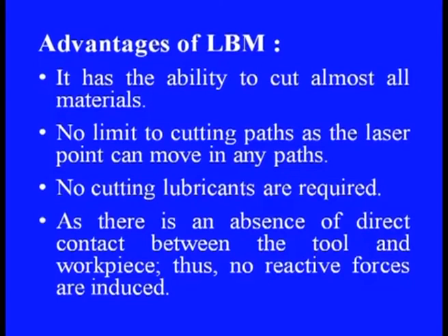As there is an absence of direct contact between the tool and the workpiece, no reactive forces are induced. As no reactive forces are induced, it is not necessary to provide work holding systems. If we can just place the workpiece onto the machine setup, it is sufficient.